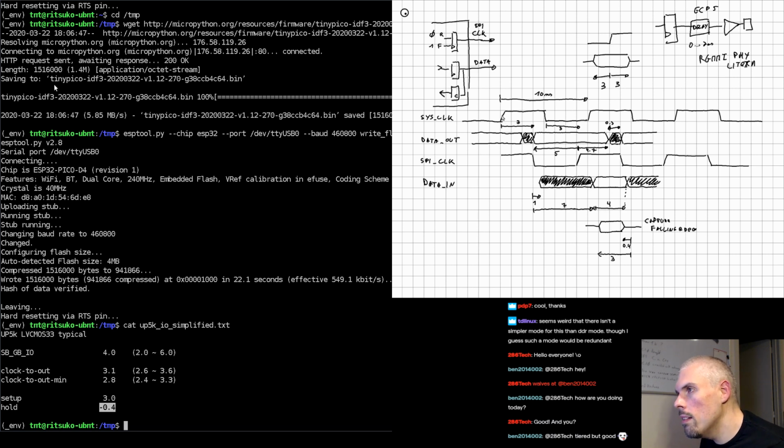So between here and here, we have 10 nanoseconds because we have 3 nanoseconds here to go from that edge to that edge, and then we have 7 nanoseconds to go from this to this edge. So from there to there, we have 10 nanoseconds by the numbers. That's where our data valid window starts. And then from here, that means that it's aligned with this edge. Now, obviously, because this is half a clock cycle, this is 5 nanoseconds, right? That's half of 10, right?